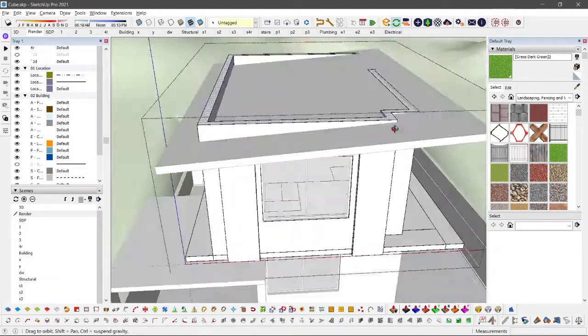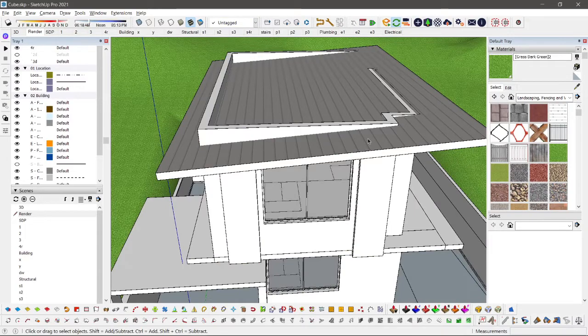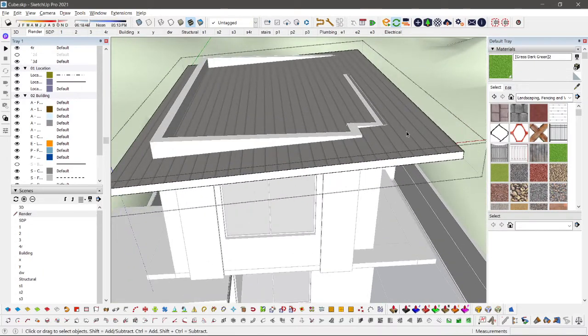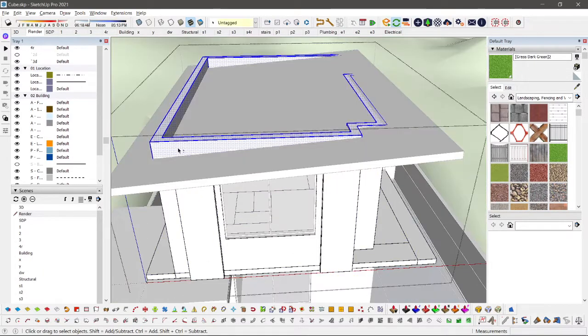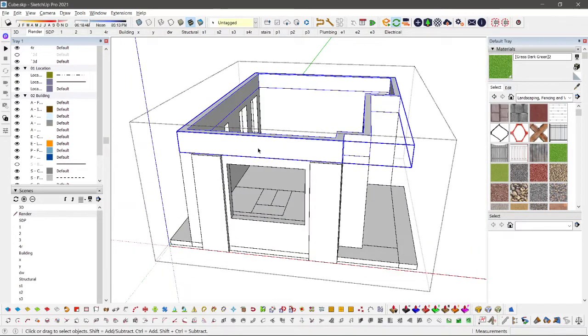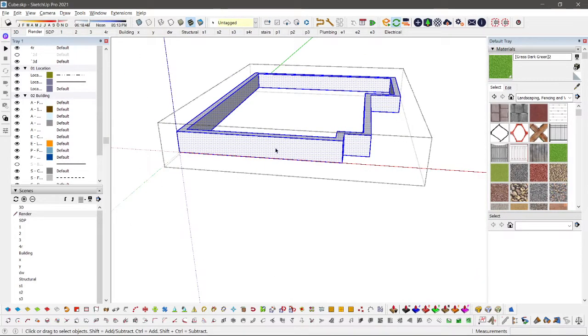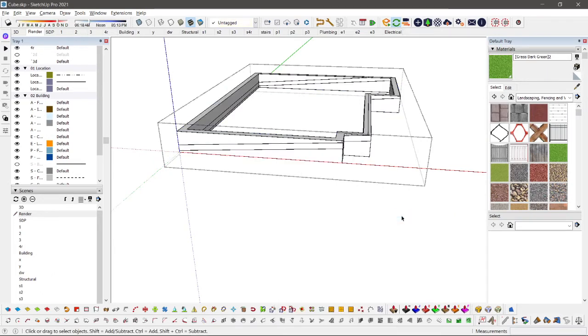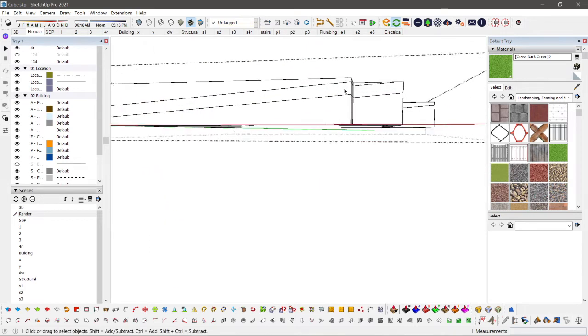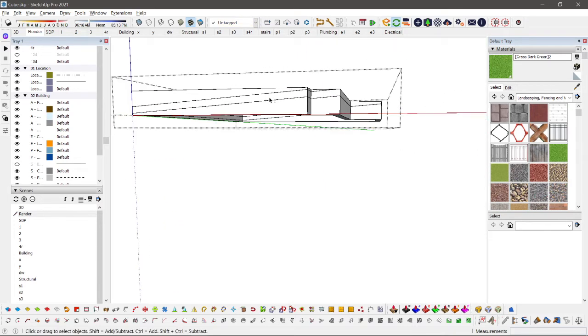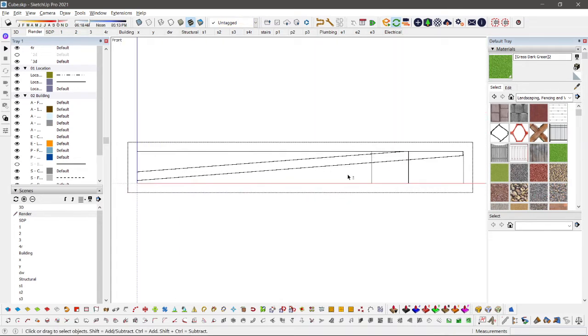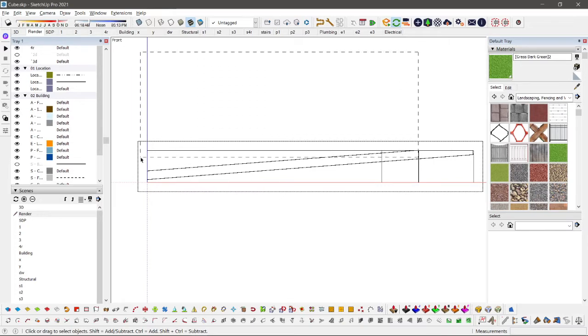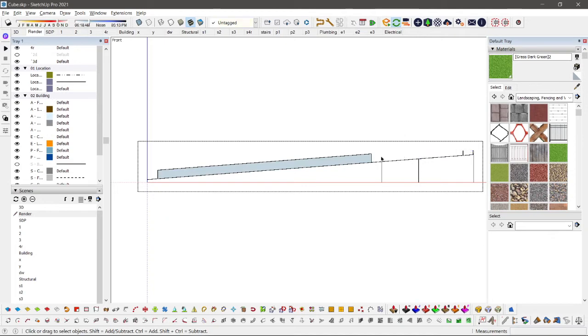And then what I do to get that cut is just, actually you can go into this, make it a group, go inside the group, select everything and put intersect faces with model, so it intersects with the lines outside. Now you have the lines from the roof, and you could start deleting them using the front view and selecting from right to left, which was in lesson 1.